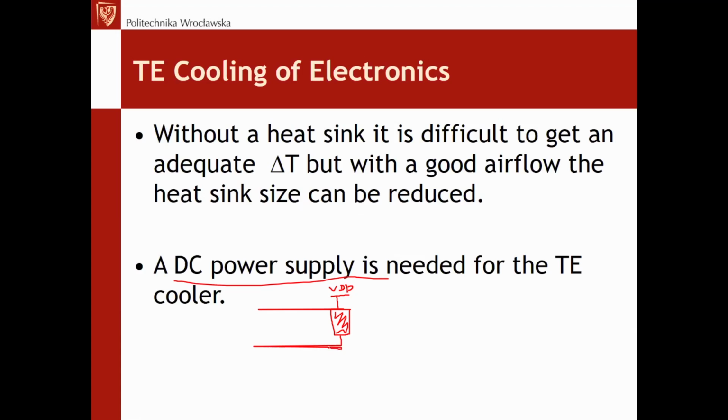The standard schematic that we are using is to use a MOSFET. Today we are using almost only MOSFETs. It is used for switching the current flow to the Peltier on and off, to switch on the heating.